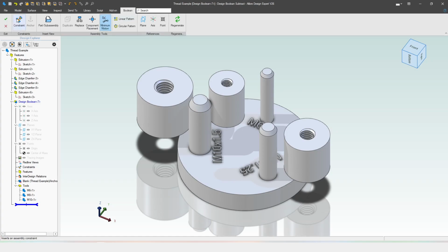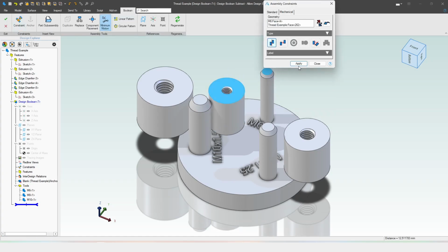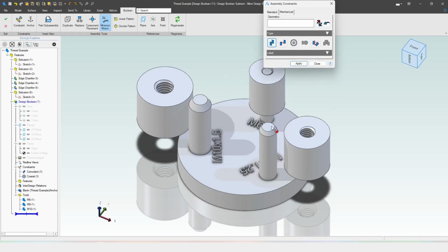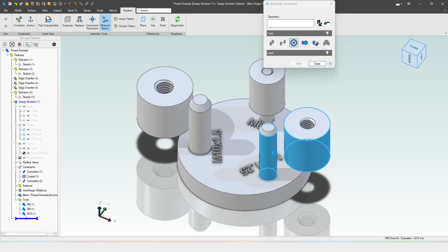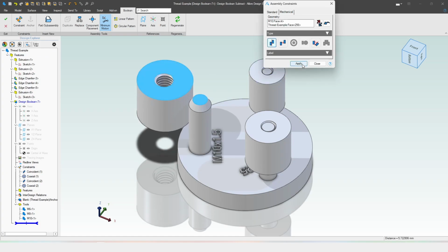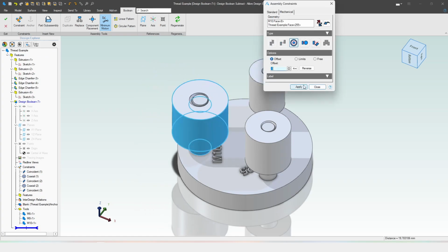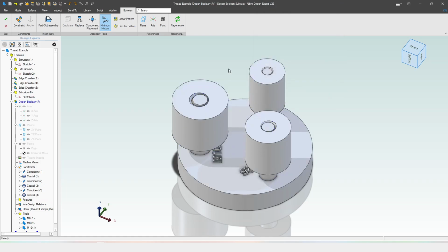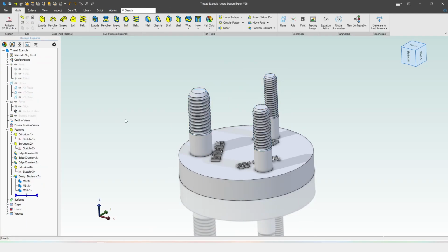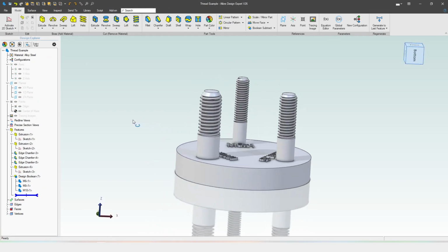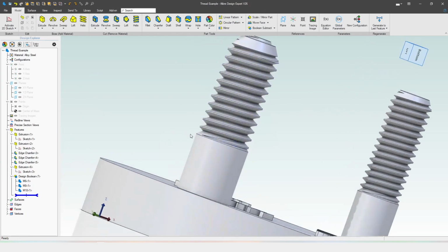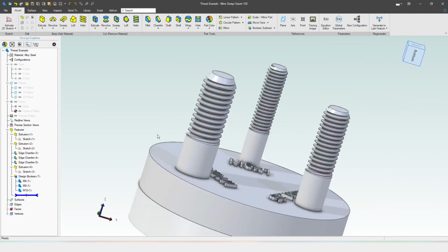So what do we do now? We go back to the Boolean and we start constraining, right? This is how the Boolean environment works. You use the same constraints as you do in an assembly, and then once you're done, the system just performs the Boolean operation that you initially selected. We initially selected subtraction, so now it's going to subtract. Okay, subtract, and 3D threaded forms, 3 different specs, all done correctly, all stopping and finishing beautifully, really nice for 3D printing.